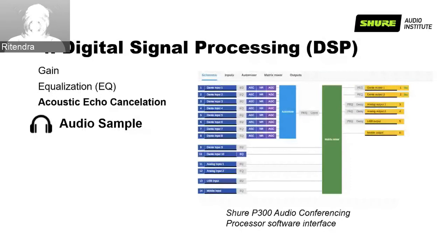And then that will be played by the speaker. So you hear your voice with some latency. That's called echo in a conference call. So how to solve that? To solve this, you have to have AEC in your DSP processing. AEC has the option to give the reference of your far end output. You give the reference, and the DSP block will understand, okay, I don't need to listen to this, whatever is coming back to the system, and it just cancels that out. So that's AEC. So let's have a look and listen to the audio demo of the AEC block, what happens when you're on a conference call and how to solve this, okay?